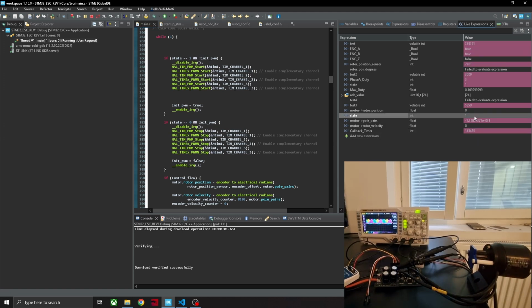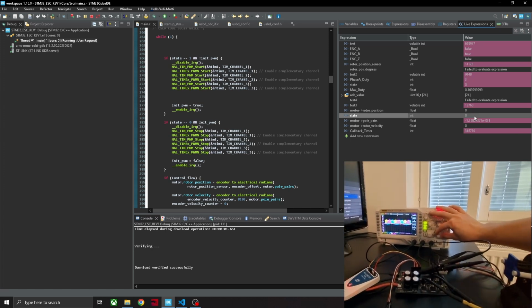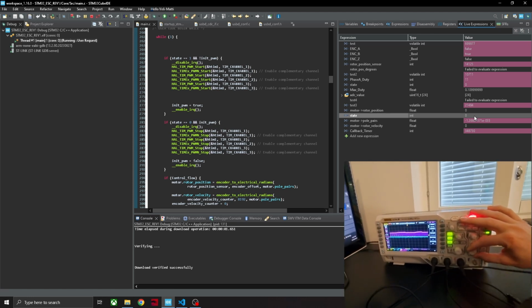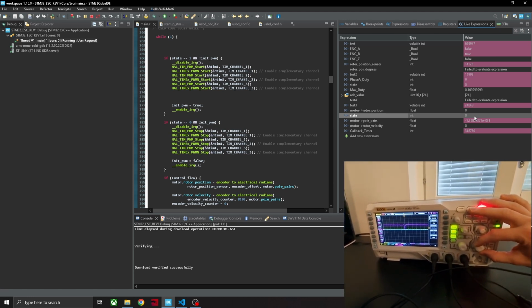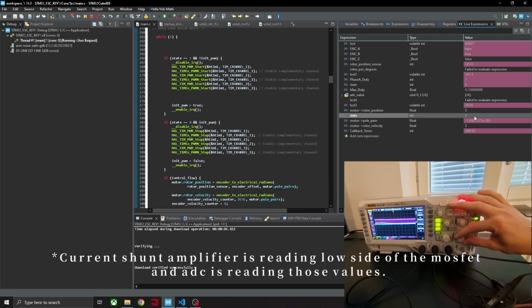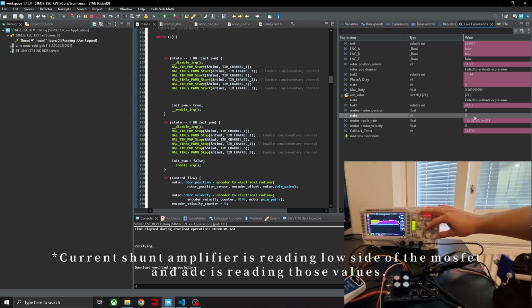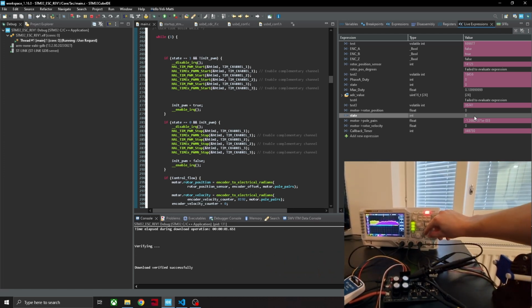And if we look on the oscilloscope, we can see that I can take a single shot from there. So if we stop it there, we can already see the current measurements. If we zoom closer, we can see that there are a lot of these spikes, and it's because the ADC is running on this low shunt. So it's measuring current on the low shunts, so it always goes to 0 and then it will go back to that value.